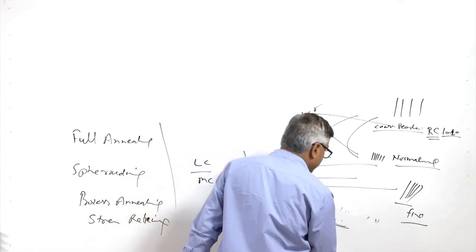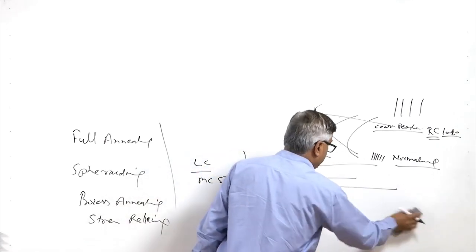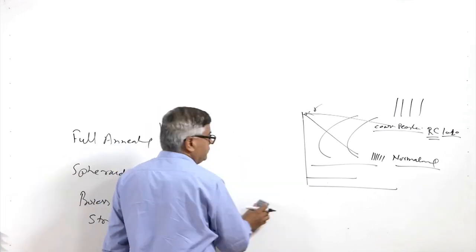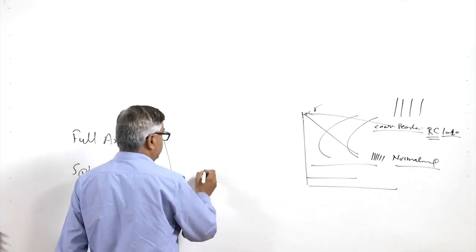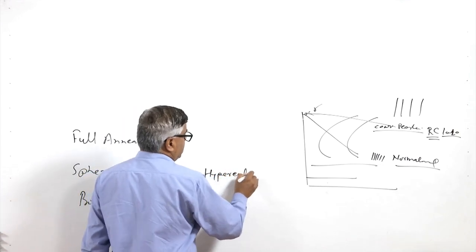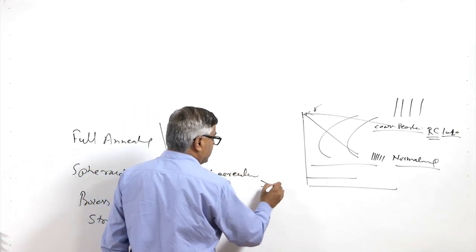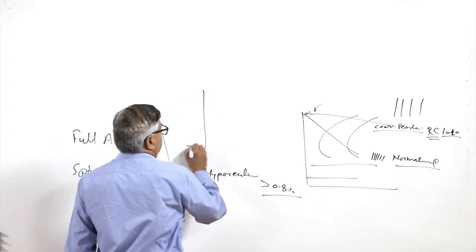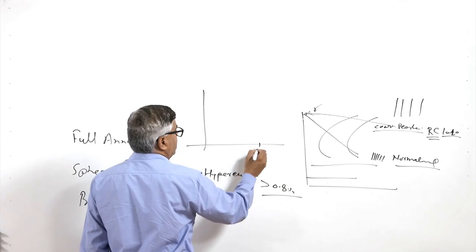But when annealing is performed, meaning lower cooling rates are applied, for the hypereutectoid steel. Hypereutectoid steel means the carbon content is greater than 0.8%. So, in that case, as per this diagram that we have seen earlier also,